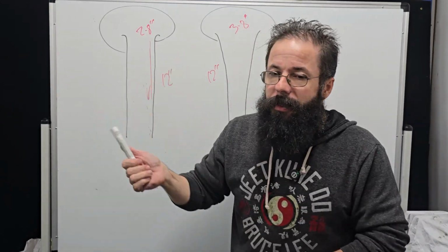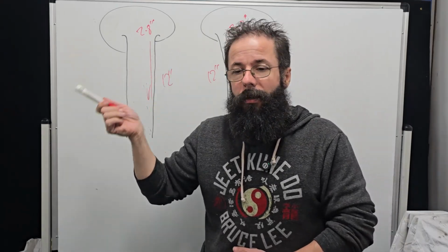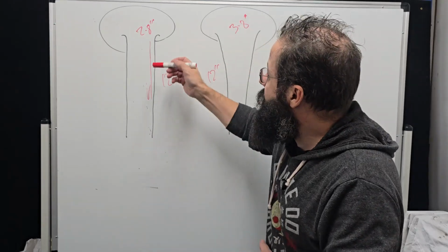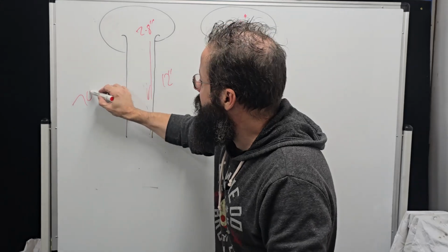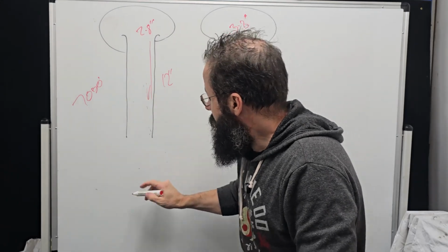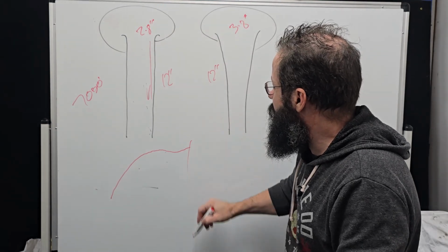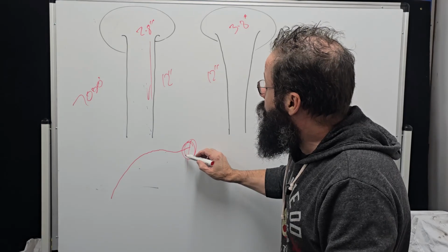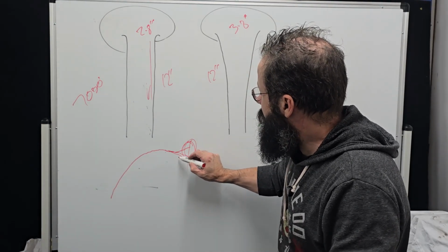This runner on the exact same engine is going to choke way earlier, probably 1,000 RPM earlier than the exact same length runner. So what you'll see, say this is the right harmonic for, let's say, a 7,000 RPM engine, and we'll see the dyno curve come up and then go down, and then we get a little kick and then we've turned it off here. Well, that was your harmonic element overriding the velocity track, because this line is velocity, okay?